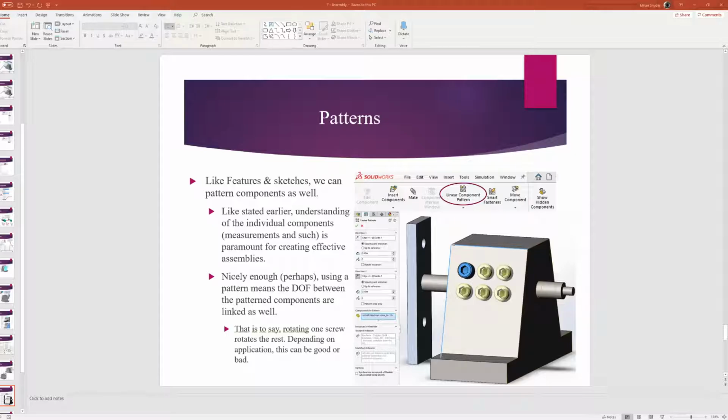Unfortunately, I placed this in an inopportune location. As you can see right here, that's our right plane, and I definitely don't want to reflect it over that plane, or else it's not going to look right. I think if I did this, they're going to be way over there. So let's not do something like that. Let's be a little bit smarter about how we mirror our pattern. So I'm going to delete that mirror. Yes, there we go. Let's figure out a good way that we can create a plane here.